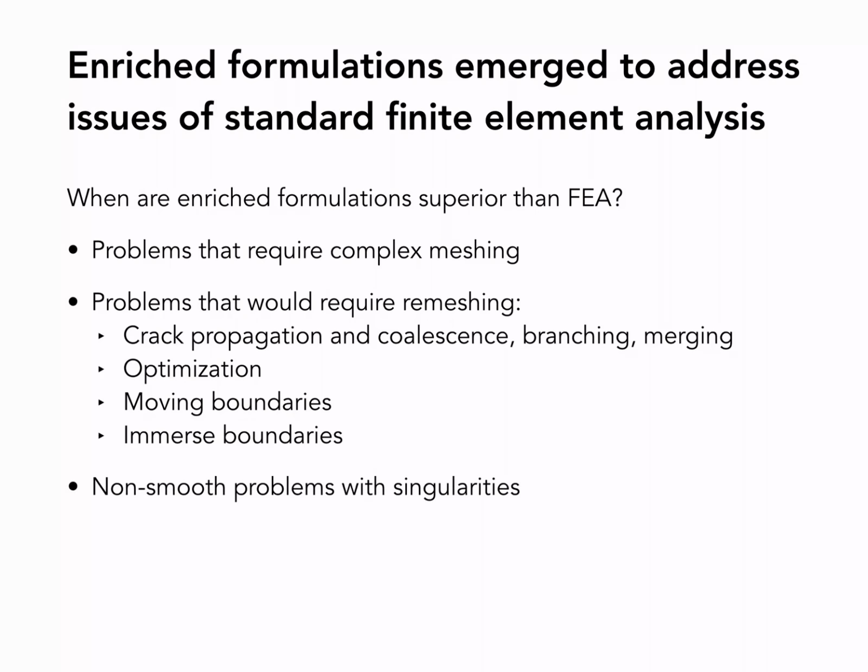Problems with singularities, that's another problem. If you remember in class, we saw those problems with singularities in category B, right? You can at most get what type of convergence with p-FEM? Linear? Well, no. It depends on your elements, but what type of convergence? Algebraic convergence. Well, it turns out that you can actually add whatever singular functions to your approximation to even improve the error and get optimal convergence. So you can obtain exponential convergence back by using enriched methods.